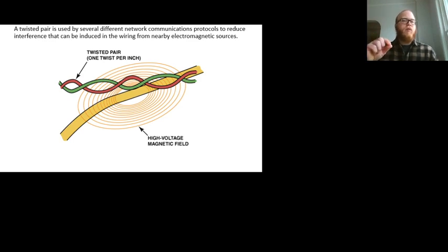They're just trying to pull voltage up and pull voltage down to make this mirrored Morse code message that it sends out. So we're not really trying to actually flow current, we're just trying to augment how much voltage is on a wire. And so that's pretty easy to mess with. And so things like twisting the wires, and we'll talk about terminating resistors as well, try to help give us a little bit more robustness to the circuit so that we're not constantly having issues.